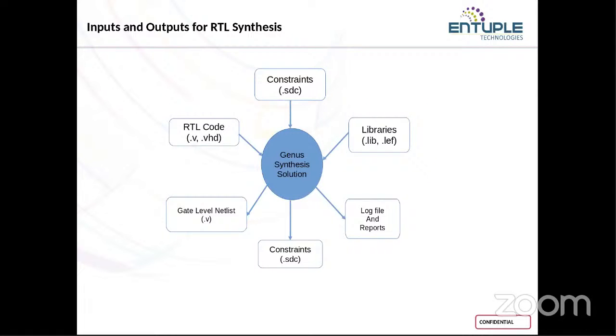For these sub blocks, you will be working on any one of the blocks, either the camera block, the memory block, or the battery block. For that particular block, whatever SDC is generated from the synthesis tool is your block level SDC file, which is dedicated only to your individual block. Whatever input we are giving is for your entire chip, and whatever you get as output is specifically only for your individual block. So that is your block level SDC file as one of the outputs from your synthesis.